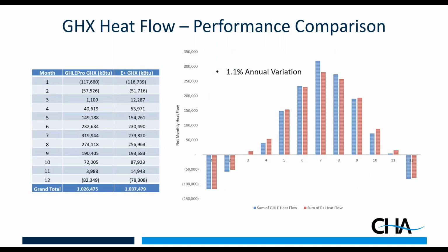So I said, let's explore that. So we took the results from that, and using the condenser loop flows, we ran them through the ground heat exchanger program, and saw that the response of how the heat's flowing back and forth matched within 1%. So we can say with fair good confidence, the ground heat exchanger program for the same loads is saying that our ground heat exchanger is sized appropriately over that long, 20-year time frame.